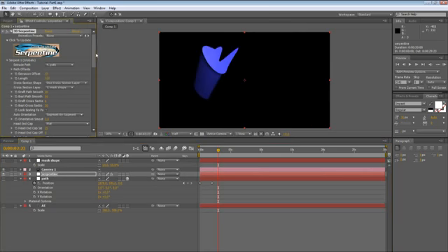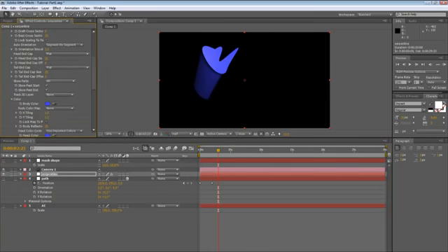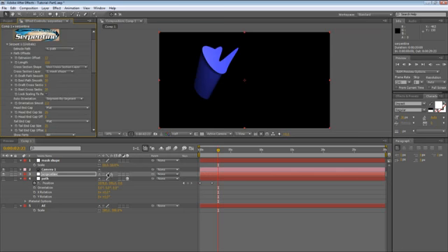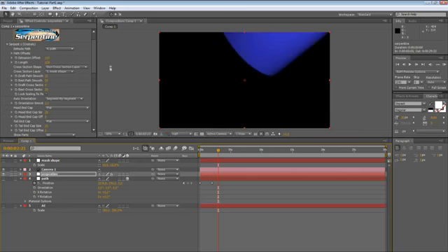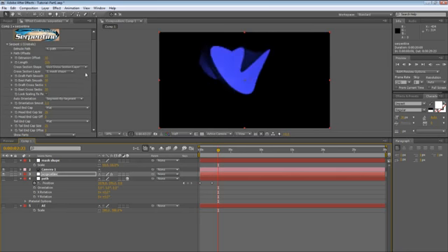Let's continue with the draft switch here in Serpentine, which is actually very important. At this point, where there's still not a lot of design added and keyframes and so on, things are still kind of responsive and fluid, even when I don't turn on the draft switch. But as you'll see when you start working with it, the draft switch is actually very important, and it allows you to really work smoothly while you're designing the structure of your animation.